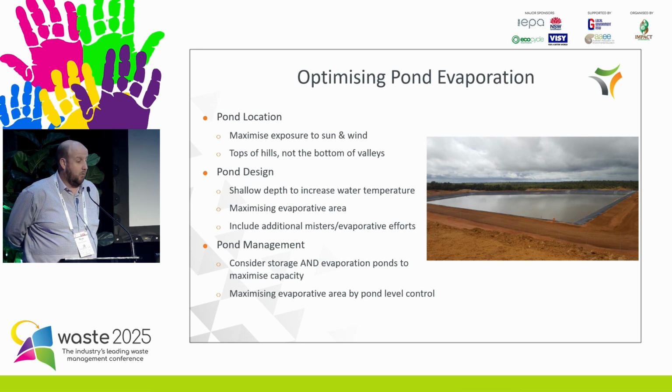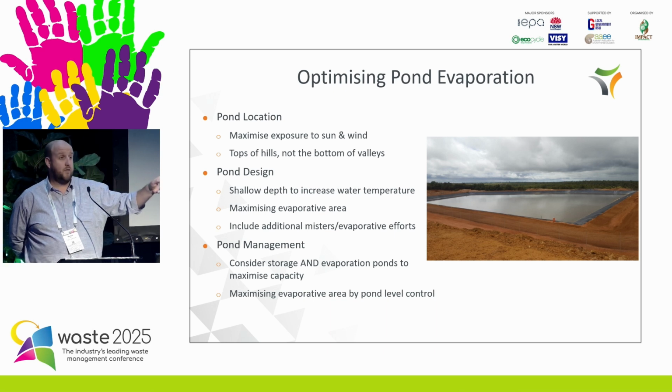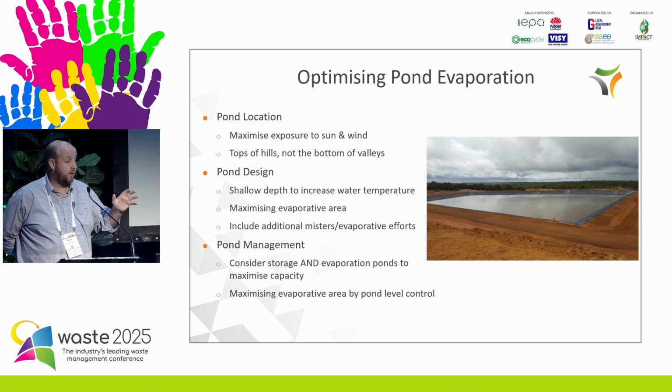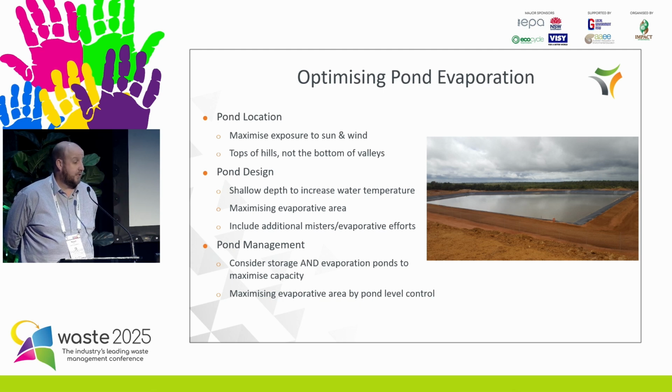Talking about ponds, I don't think I've been to a landfill, well, actually probably one or two very small ones, that have no infrastructure for leachate at all. Whether you're using evaporation or just storage, you're going to have a pond. So it's very important that we think about this when we are designing these facilities. Location is key, particularly if we're trying to encourage as much evaporation as possible. So not in the bottom of a hill, but at the top of the hill, not in the bottom of a valley or something like that, minimising the amount of sunlight and wind that can get in there. Be very mindful of whether your pond is supposed to be for evaporation or storage, because the designs are very, very different.